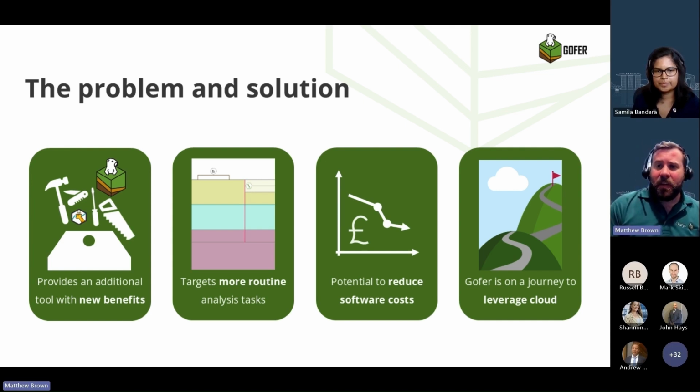So some of our existing geotechnical desktop suite is very quick and easy to use, but in some cases was lacking some of the sophistication in output and calculation methods and so on. For example, Oasys Frew is very good for flexible retaining walls, but it doesn't give you much information about ground movements away from those walls for things like damage assessment and so on. Hence the need for an easy to use geotechnical finite element program that will give you that level of sophistication without the time penalty in getting up to speed with a very detailed and sophisticated finite element package.